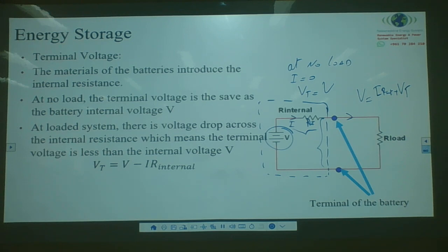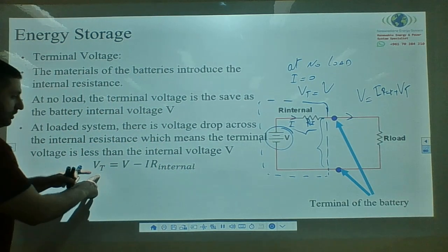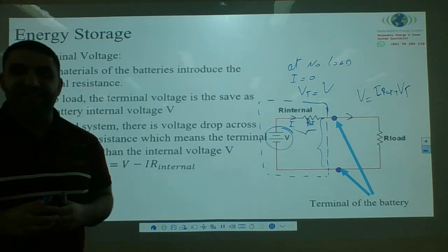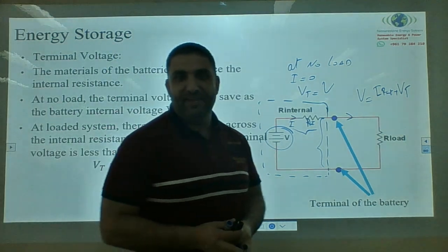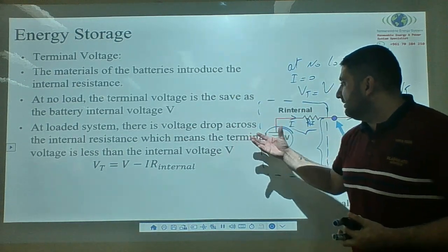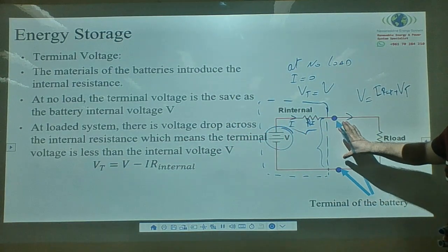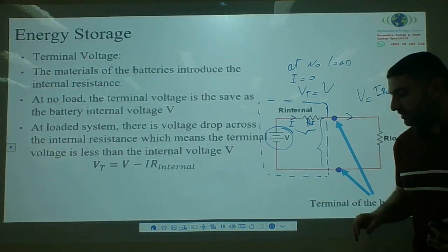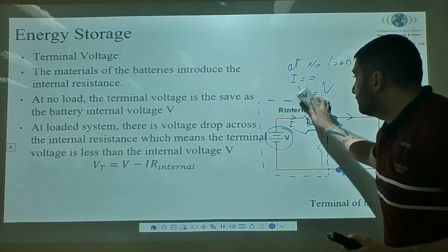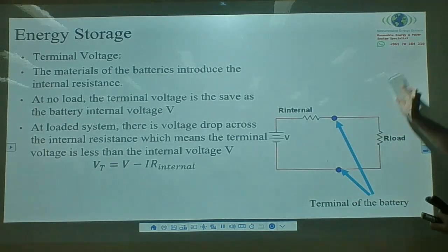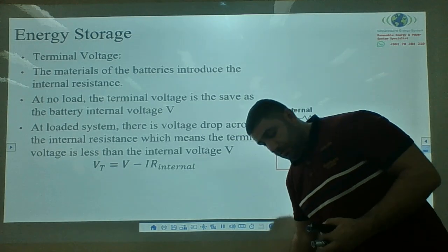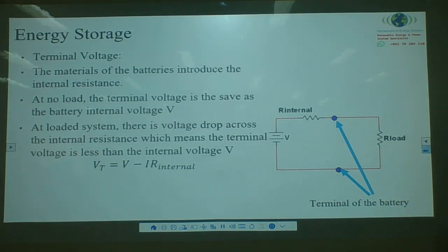So it's very important. See, now, the terminal voltage is what my devices will read. You will see later on why this is a very important concept. It's very important to understand the terminal voltage of my battery under different loading conditions. I hope that's clear now, the relationship between the terminal voltage and the internal resistance, where Vt is the terminal voltage and I is the load current.